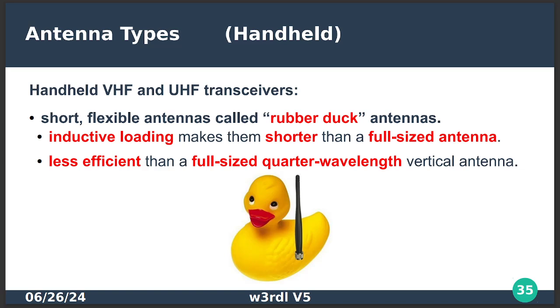I've got 3 of these antennas, and I've tested all 3 of them, and they all measure just ridiculously different. One of them at 2 meters is like 8 or 9 to 1 SWR. So kind of high, but these things only radiate 5 watts, so it usually doesn't reflect enough to cause any damage.